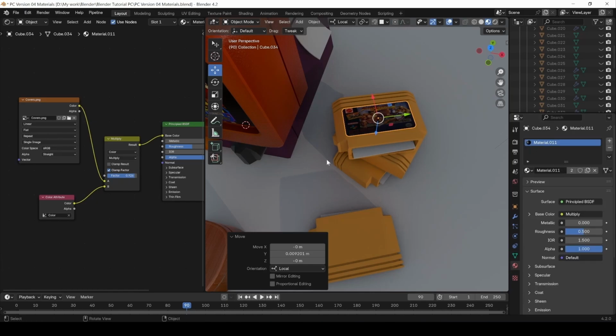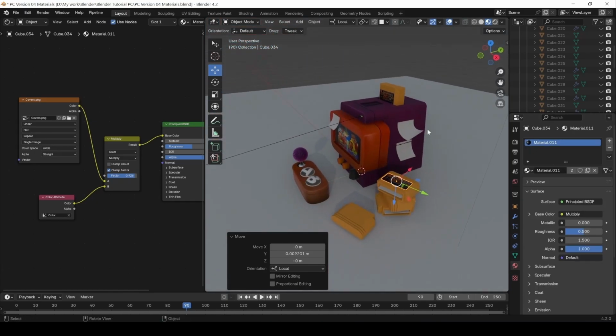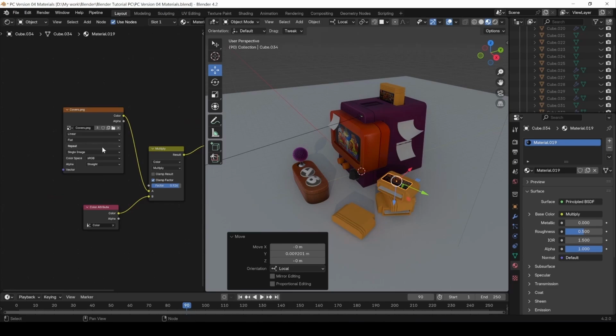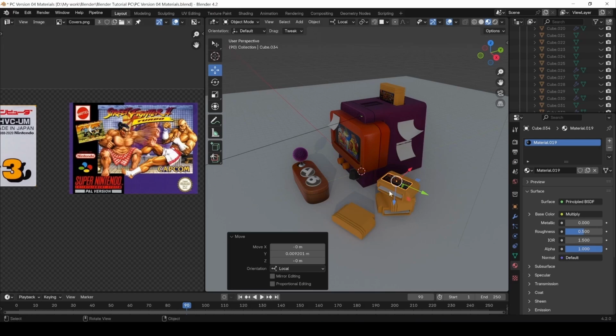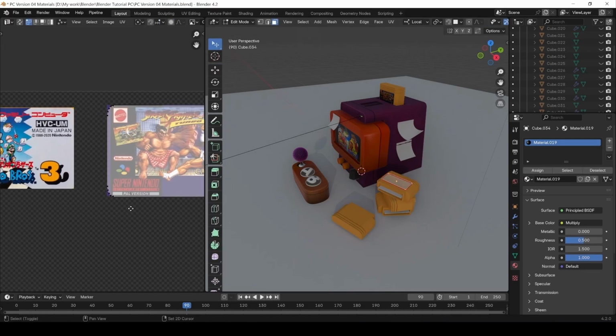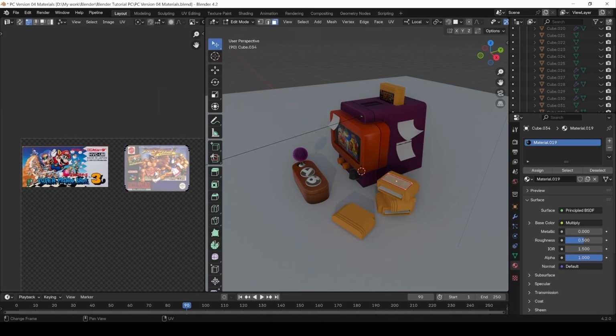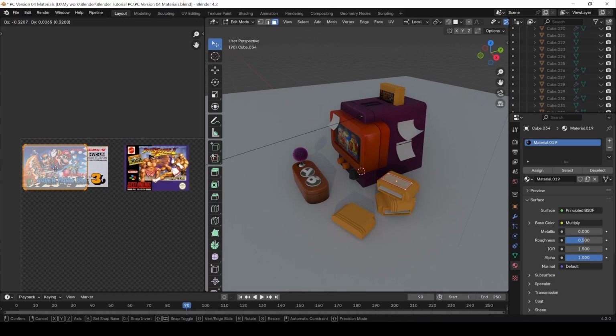So now this is basically using the same material. If we go here, it's using the same material as this one. So let's change this. Let's click here, and now we leave the same image, we leave the same details basically, and we just go to UV editor and 3 to choose the face, and instead of this face being here, let's go to face, select this face and just put it right here.